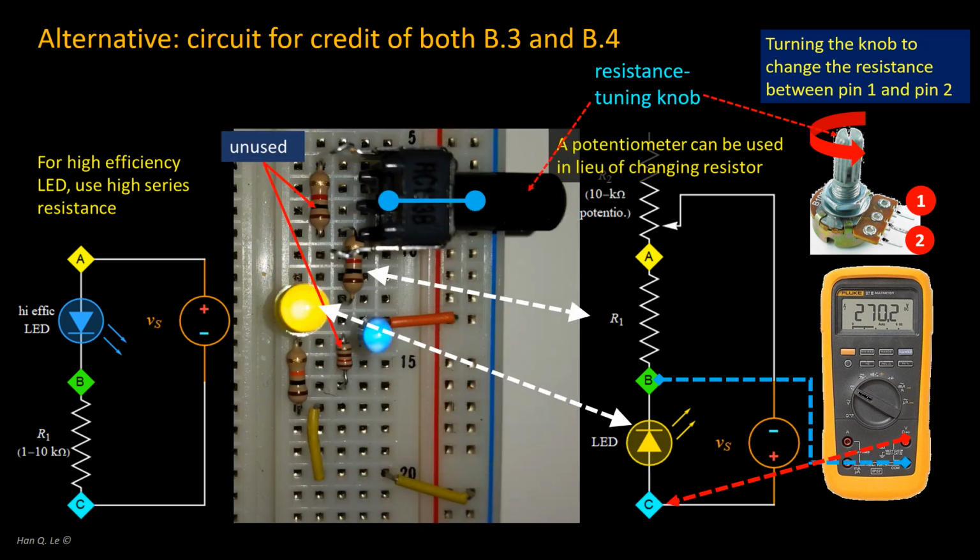Tune the potentiometer the other way slowly while monitoring the voltage across R1. You should see the LED getting brighter. Use Ohm's law for the LED current, and for each value of current you write down, measure and record the corresponding voltage across the LED. Remember about the polarity and change the sign as needed. Tabulate and graph your data, at least 4 points, in your lab report.